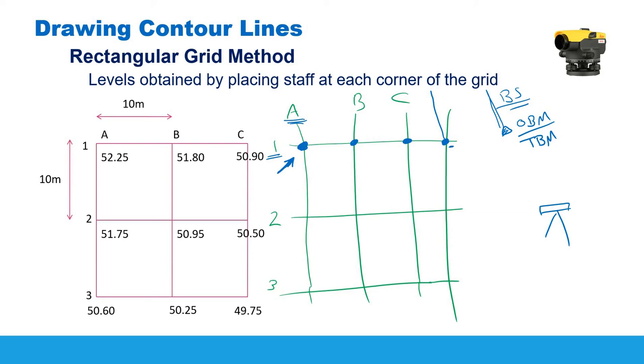And now you are going to collect intermediate sights over these intersection points. You will locate the leveling staff at each point, and then you collect a reading to complete the leveling table. All of these readings could be considered intermediate sights. When you finish all of these intersection points, you are going to take the last reading over the temporary benchmark or the benchmark that you started from, and this could be considered as a foresight.